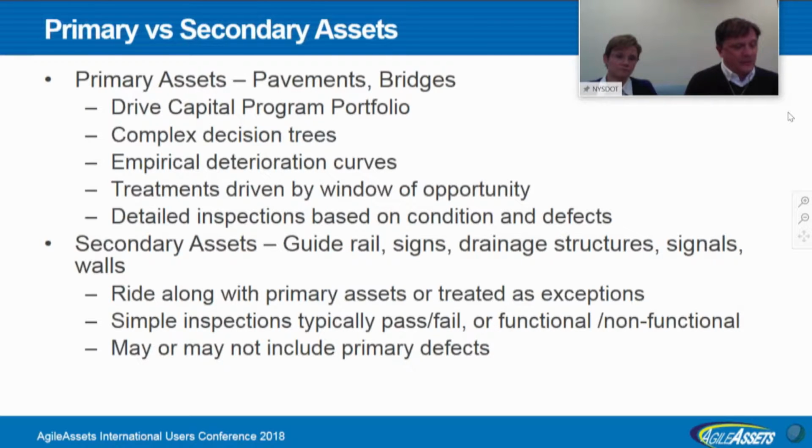We write our program update instructions around those. We know how these deteriorate empirically over time. We've developed complex decision trees for both assets. They are also time-based in terms of how we determine not just what treatments we do, but when we do them. We tend to try to do them in the latter third of the window of opportunity for treating those. And we have very detailed inspection programs for both bridges and pavements. That really drives a lot of the program.